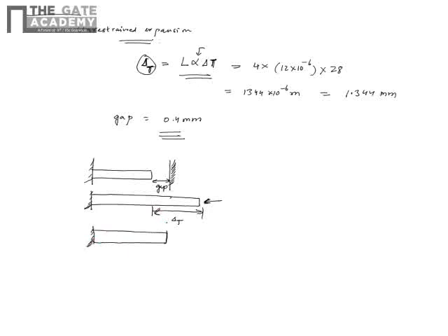The remainder, delta C, is the compression due to the compressive load developed by the wall. So the net expansion is only the gap, 0.4 mm, and delta C is provided by this compressive force.